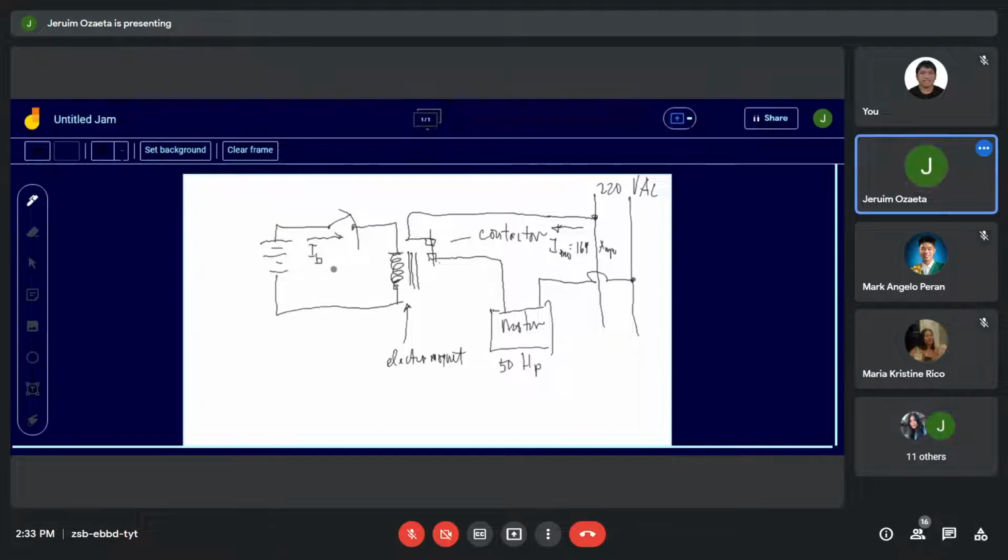And the battery, if this is 12 volts, a control voltage of 12 volts or 48 volts, this only drains, if this is 5 watts, that goes to only about 5 divided by 12, about 400 milliamperes. Okay, 400 milliamperes. Because the relay is only 5 watts.